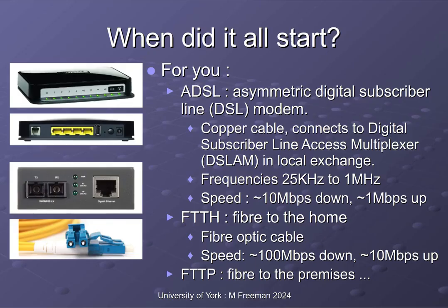So now we have a basic technique for transmitting digital data across our phone lines. But because the phone lines are limited to roughly 4 kHz bandwidth, that limits our bitrate to a few hundred bits per second. However, over time, we came up with some ingenious ways of encoding our ones and zeros. So we moved away from frequency shift keying to phase shift keying.